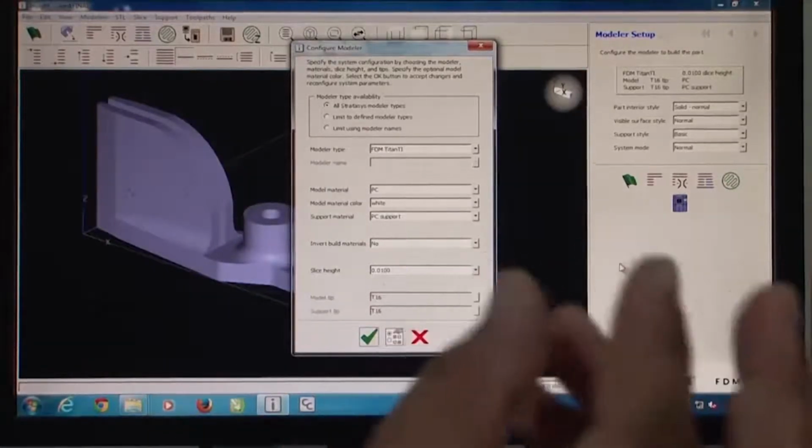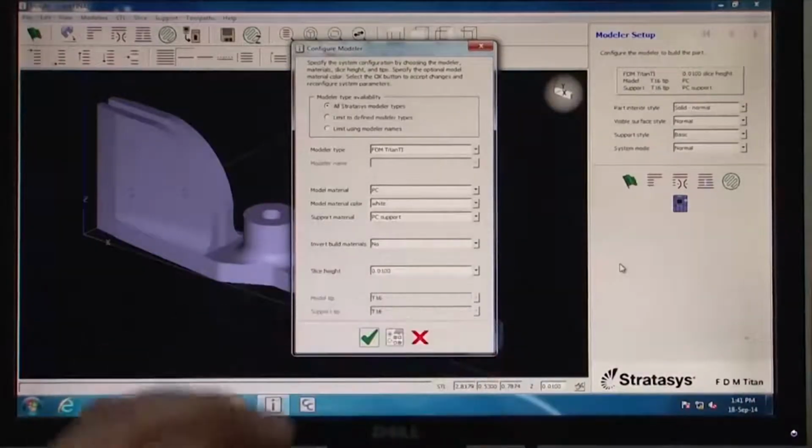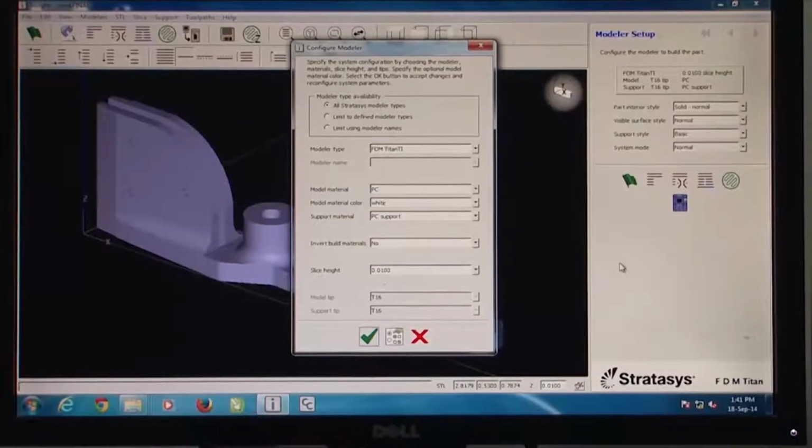So, if the nozzle is slightly higher in diameter, in that case the dispensing would be faster, and therefore it can go to a higher layer thickness. Okay. So, it all is defined by that layer thickness, that how the nozzle selection, etc., to take place.